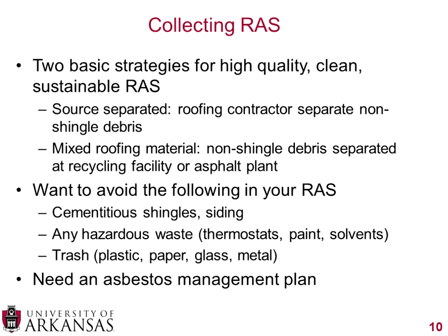Another comment is that the asphalt used in shingles is typically air blown, and I did not point that out. Thank you for bringing that up, Steve. So in the asphalt process to make shingles, you air blow the asphalt cement, which is what makes it so much stiffer, and that accounts for the very high PG grade.